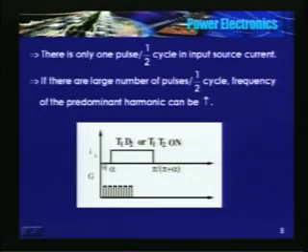So maybe killing two birds with one stone, because I am starting the conduction at the positive zero crossing, displacement factor becomes unity, and I have a large number of pulses. So in other words, the total distortion comes down. If the total distortion comes down, power factor improves.